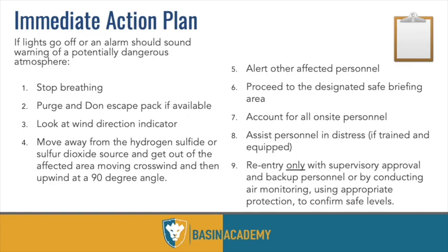Next step is to alert affected personnel. Make sure everybody knows that there's some release once you're safe and protected from it. You don't want to let people know as you're getting gassed and you go out. That's not a good situation. Go to the briefing area or the muster point. Account for everyone that's on site.